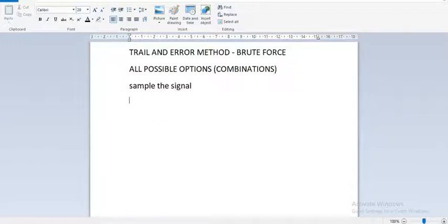Maybe you can take about 100 units of the signal, then find the average. By taking the average, you read the ADC 100 times and add it up, then divide by 100 to get the average. That is what it means to sample and get an average reading.